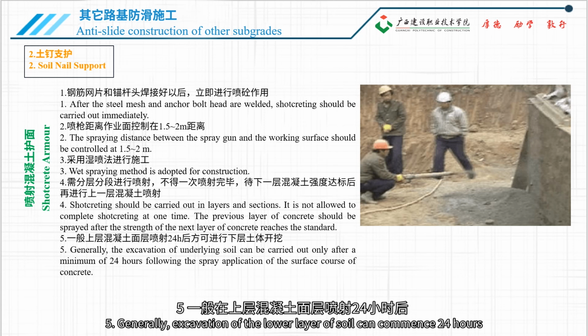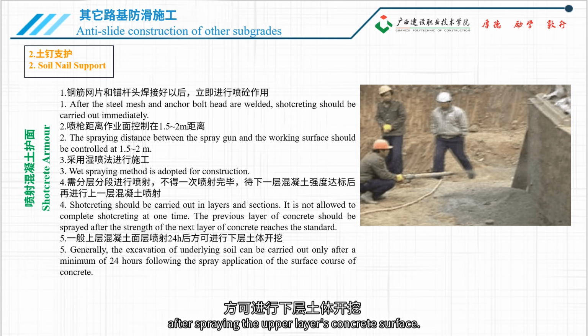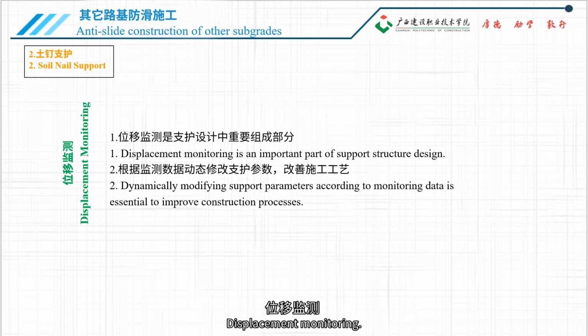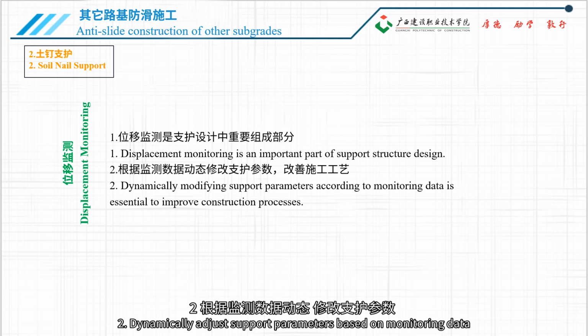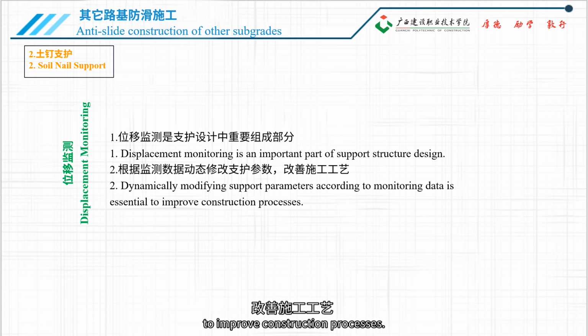5. Generally, excavation of the lower layer of soil can commence 24 hours after spraying the upper layer's concrete surface. Displacement monitoring. 1. Displacement monitoring is a crucial component of support design. 2. Dynamically adjust support parameters based on monitoring data to improve construction processes.